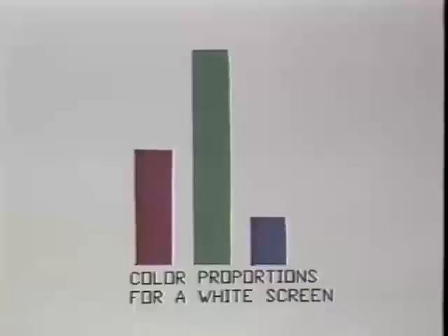When you are satisfied with the color of the display, re-enable the drive controls and turn the screen grid back to the mark. The video should now be normal brightness. The color may change as the brightness comes up, but the drive adjustment will correct that. At this point, you can proceed to the drive or color temperature adjustment.